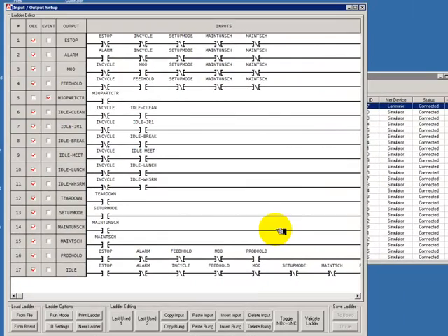So with that, what we have done is really physically configured the particular board to be able to communicate the different information that we need to. We can copy input rungs, we can create rungs, paste them, edit them, delete them, do that sort of thing. We can toggle, we can validate the ladder, and validate the ladder simply means it goes through and checks to be sure everything makes sense in terms of the ladder, its status.